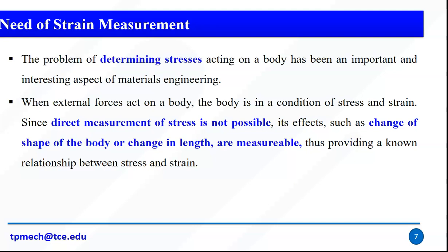So what are the causes? When stress happens, it may be the change in length, change in the dimensions. So its effects, such as change of shape of the body or change in length, are measurable, given a known relationship with stress. So if we measure the causes, then we can measure the stresses. Stress cannot be measured directly, but if we measure the causes of stress, then we can measure the stress. So this is the need for strain measurements.